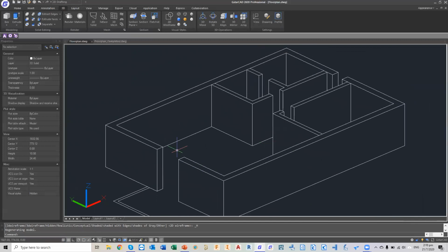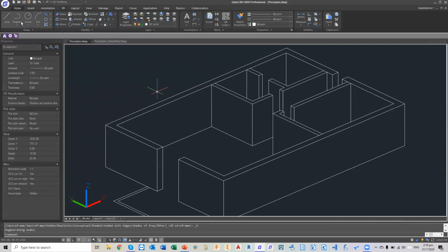You can see some openings at the outer wall and the inner wall, because the openings are meant for creating the doors. The first thing I'll show you is how to create the parapet, the wall on top of the door, to close it at the top of the door. Over here, I will use the rectangle tool to draw the shape that I want.